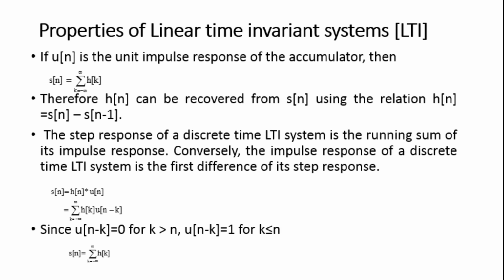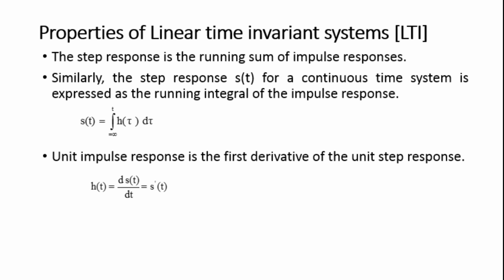Since u[n minus k] is equal to 0 for k greater than n, and u[n minus k] is equal to 1 for k less than or equal to n, then s[n] is equal to the summation k equals minus infinity to n of h[k]. The step response is the running sum of impulse responses.